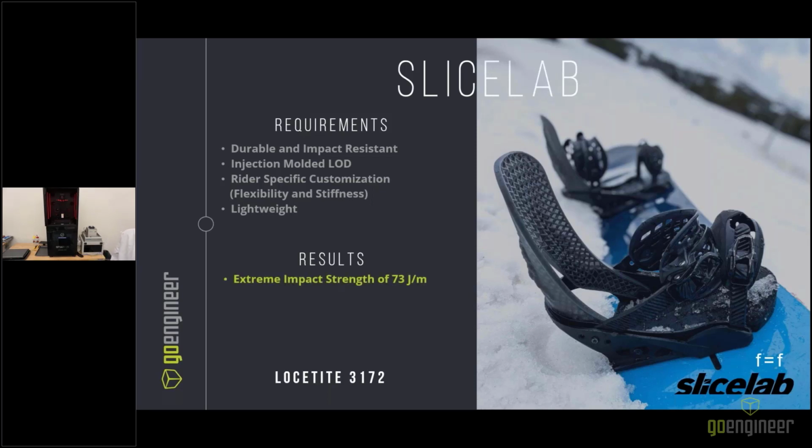The material used has an impact strength of 73 joules per meter. It has over a 100% elongation at break, meaning there's an extremely high energy absorption and rebound. The lattice structure saves 58 grams from this high back. When you're looking at sporting equipment or more exotic type markets, every gram matters. And the more you can save, the better you will perform.